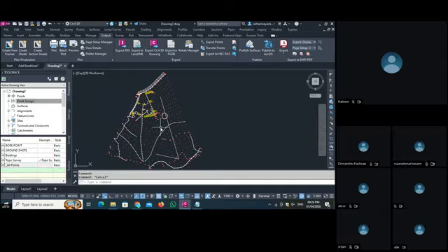So these three things we check in our surface. Then we will go into the surface analysis. The first one is the slope analysis, then the second one is the terrain behavior. When you are working, it is very important to do a slope analysis because there is water that flows on the surface. So how to set your contour as per the water line.